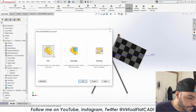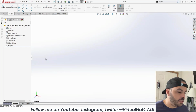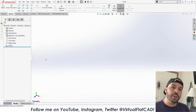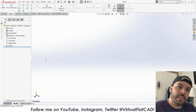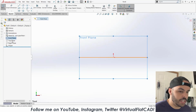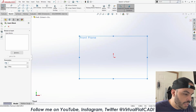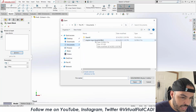Start a new part. And actually, I prepared the SLUGME logo for this event. I traced it beforehand and I saved it to a SOLIDWORKS block, which I recommend if you work at a company and you like to stamp your logo on the parts that you make. Definitely trace your logo, put some effort into it, and then save the block. And the nice thing is, watch this. I'm going to start a sketch on the front plane. Command you're looking for is insert block. Insert block, browse, go to where you keep it, which I just put in my documents.